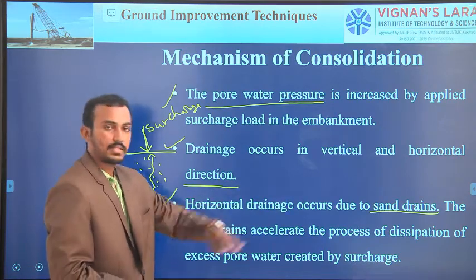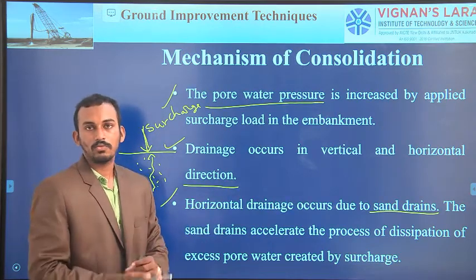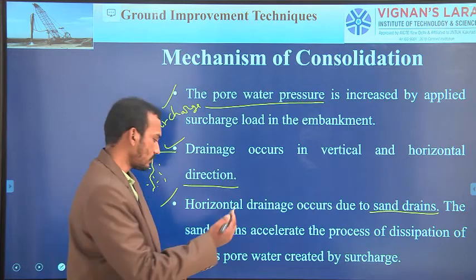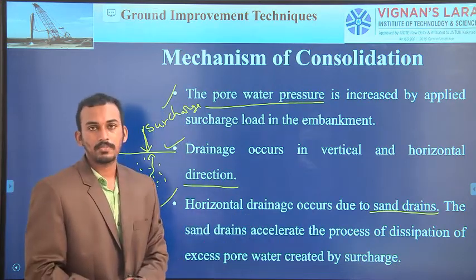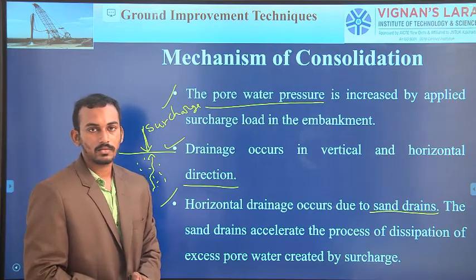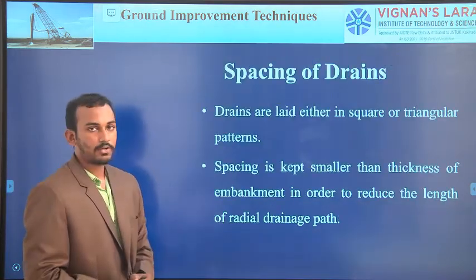If you do not place any sand drains, the water tries to move in the upward direction only. The sand drains accelerate the process of dissipation. Dissipation means removal of water. So this is the mechanism of consolidation.